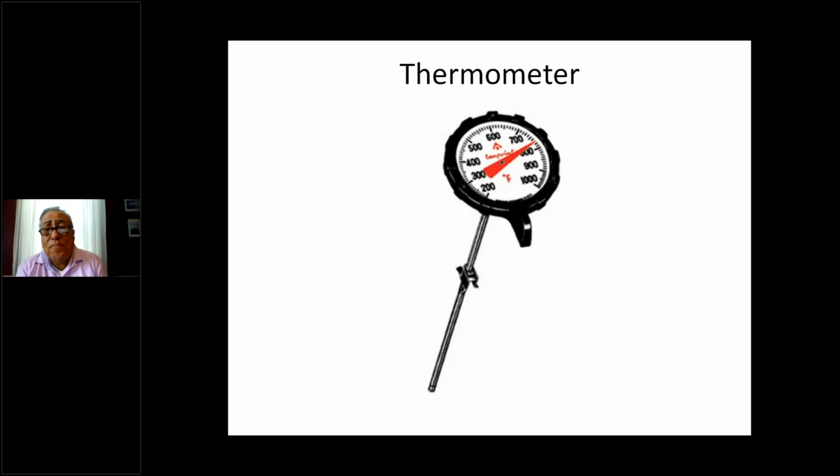And then finally, you needed to check the temperature of the flue gas. And you see here, we're approaching 800 degrees. That was pretty common back in those days to see very high stack temperatures. So you had to do these 3 things: test the smoke, check the CO2 level, and see what the thermometer gave you for stack temperature.